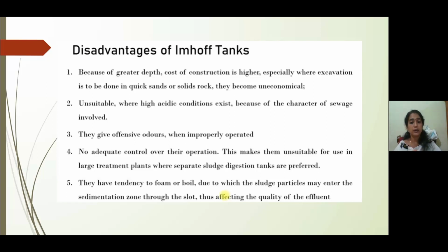There is no adequate control over their operation. This makes them unsuitable for use in large treatment plants, where separate sludge digestion tanks are preferred. They have a tendency to foam or boil, due to which sludge particles may enter the sedimentation zone through the slot, thus affecting the quality of the effluent.